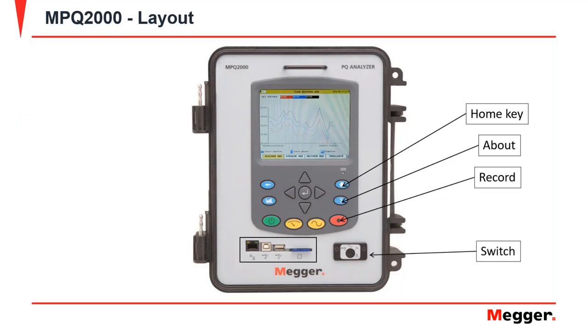There's a switch here which has two positions: aux and VA. In the aux position, the unit relies on an external source of power, so you would need to connect the power cord to the recorder and connect it to a power outlet. Typically, when you take this unit out in the field, you leave the switch on the VA position, which means that it's going to rely on the voltage that's coming in on the VA channel.